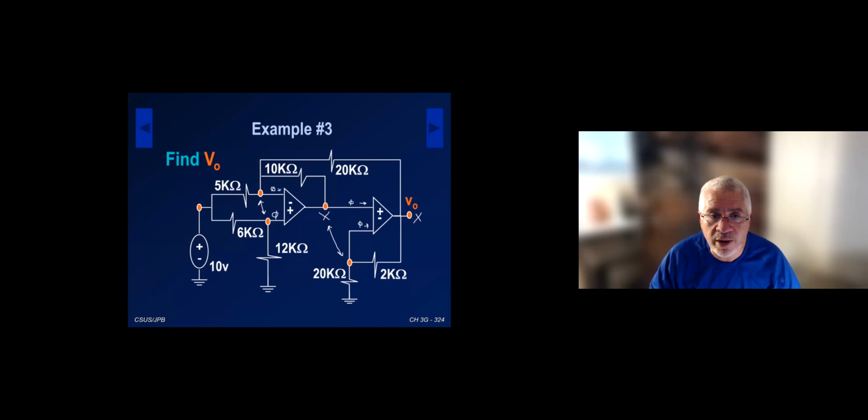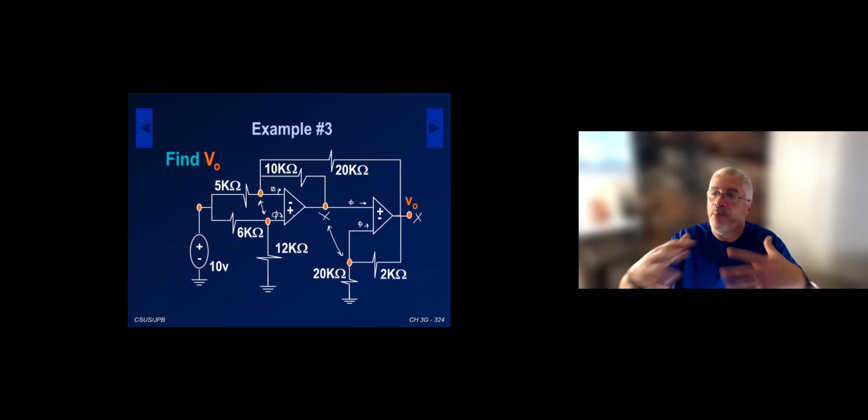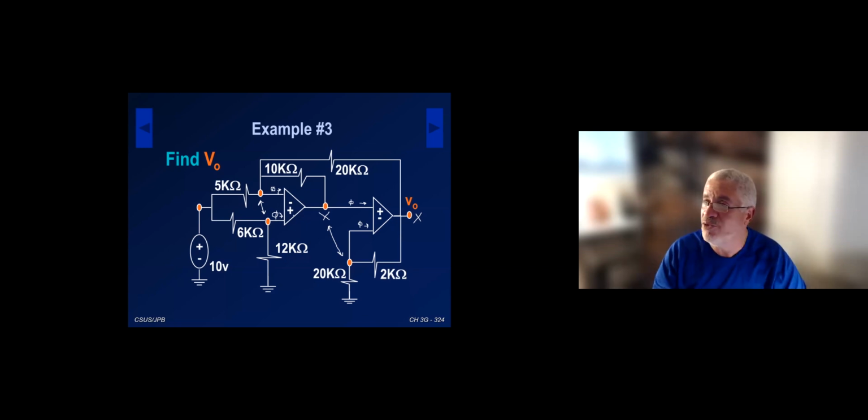Okay, so zero current going into the input of the op amps, because it has a lot. So these are the rules that we're applying on top of nodal. Obviously, you can see my reference node is already selected, so that basically is calling for nodal, and then we're going to solve it regularly.